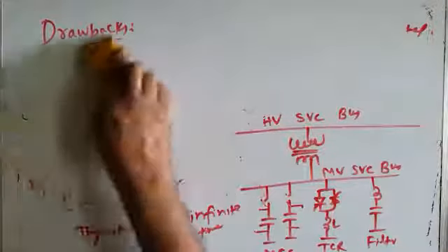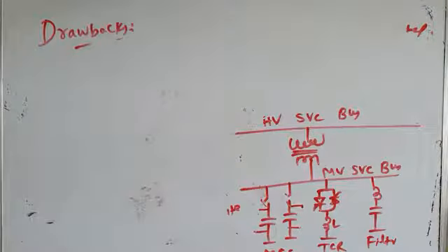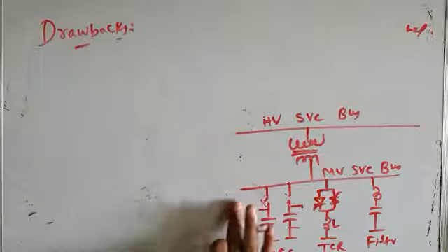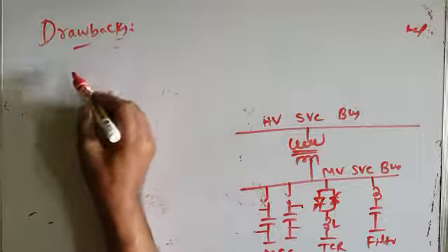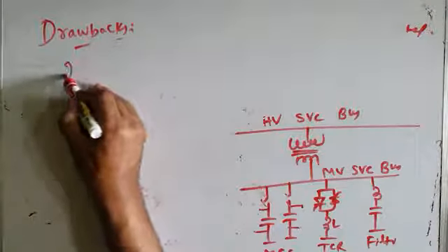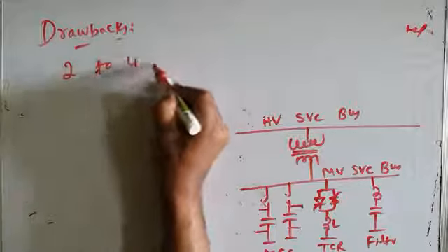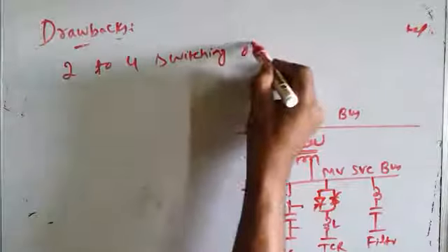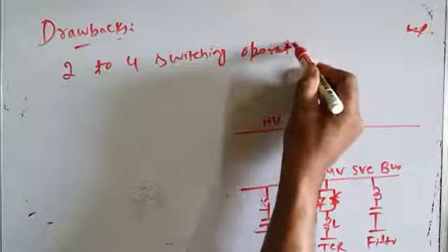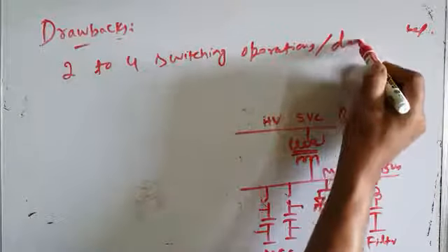So generally that's why I said in the beginning itself that this MSC, TCR, SVC is suitable only in those applications where only a few operations are involved in a day. For example, they are used in those applications where 2 to 4 switching operations are required per day.